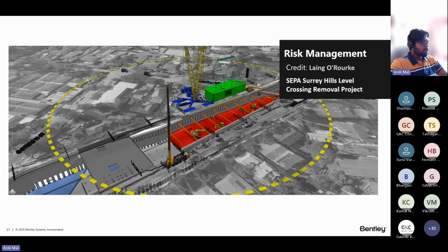To limit the chance of time overrun and to reduce the risk associated with traditional construction on-site, the structural components were constructed off-site, and the design for manufacture and assembly (DFMA) approach was taken. This approach was mainly taken for the high-risk activities which are a part of the critical path.